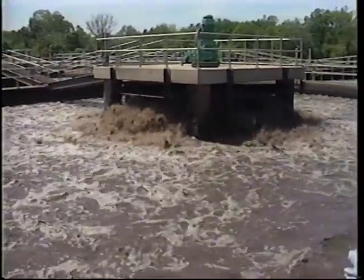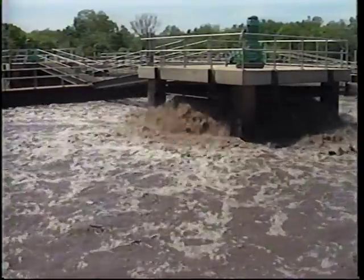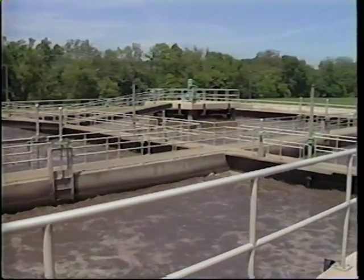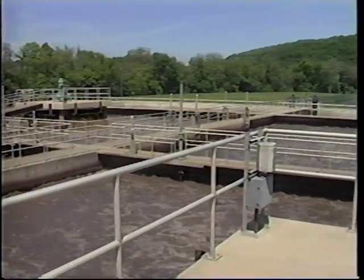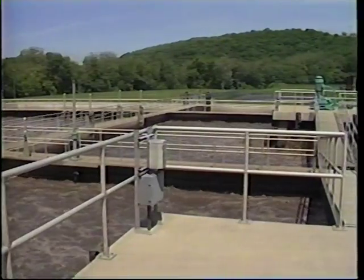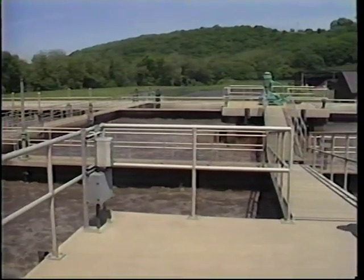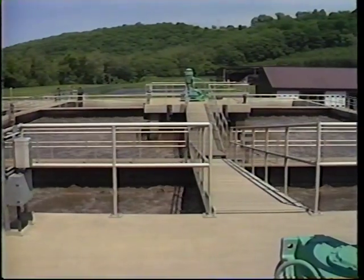If you divert all the influent wastewater and return activated sludge to the inlet of the aeration tank, you will be operating in a conventional activated sludge mode. If you divert the return activated sludge to the tank inlet and the influent towards the latter 2/3 of the aeration tank, you are operating in the contact stabilization mode. With this flexibility, you may be able to treat peak flows or higher loadings at your facility in the contact